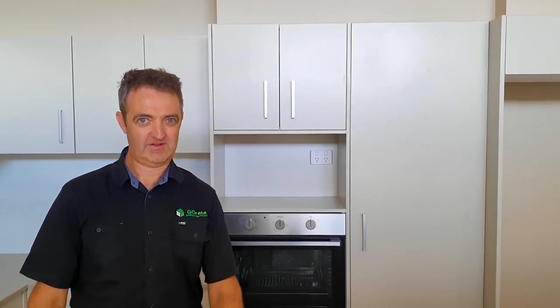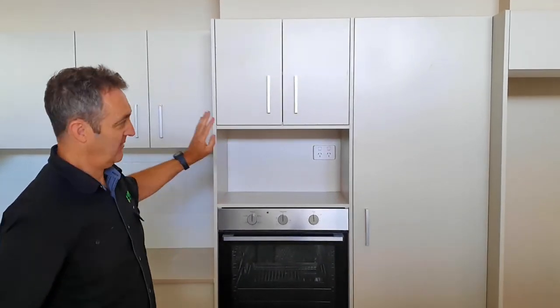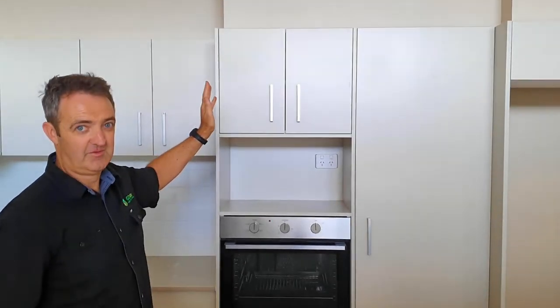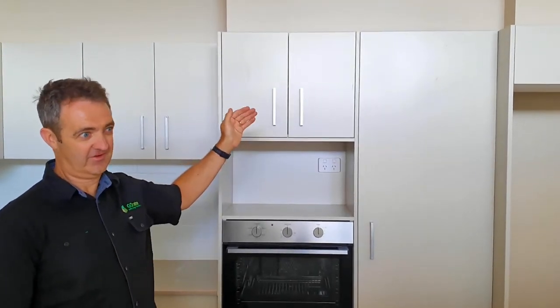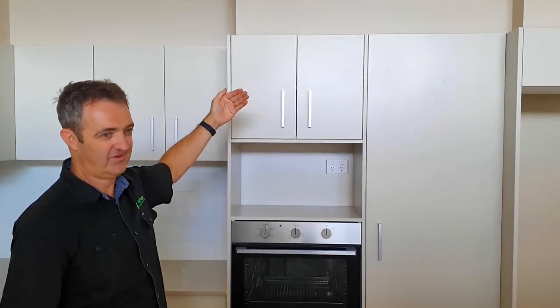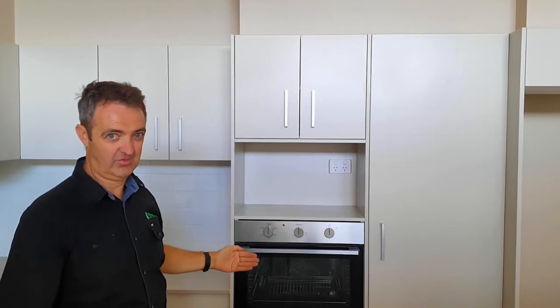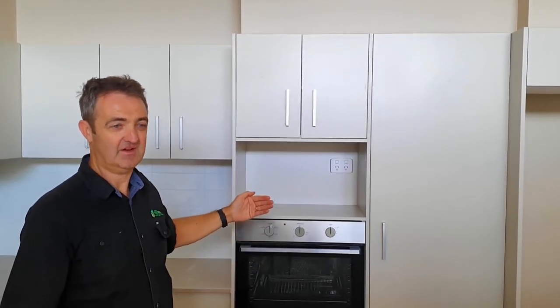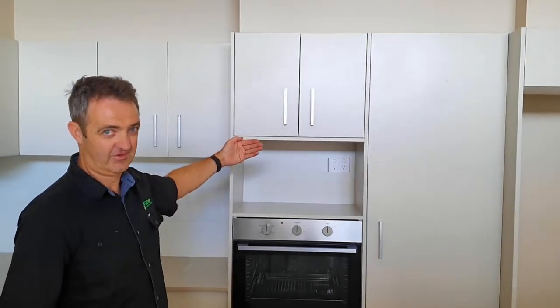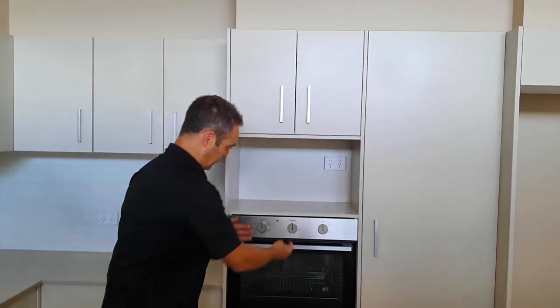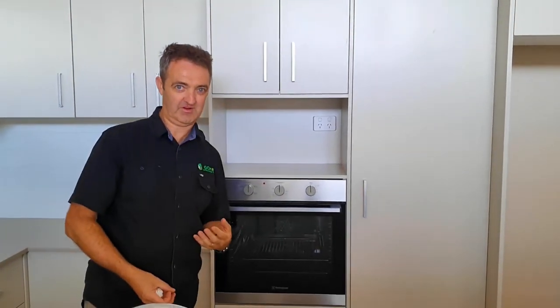Another point of air leakage is cabinetry. Not the cabinetry itself really, but quite often what happens when you're building or installing cabinetry, the plasterboard is often not behind it. So it's really better to sheet the whole wall with plasterboard and deal with that as your air barrier rather than rely on joinery. Because as soon as there's a gap, you're going to get leakage. And quite often there's air just gushing through from behind here.